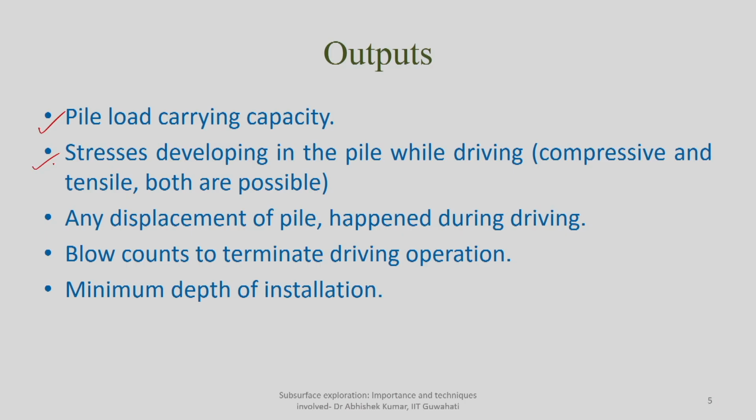Second thing, the stresses which are developed against this impact load, which is particularly the drop of the hammer. What are the stresses developed? Both compression as well as tension can be measured. Second thing, any displacement happening while driving, so lateral displacement which may be responsible for bending of the pile also. That can also be detected once you put the sensors on diagonally opposite ends.